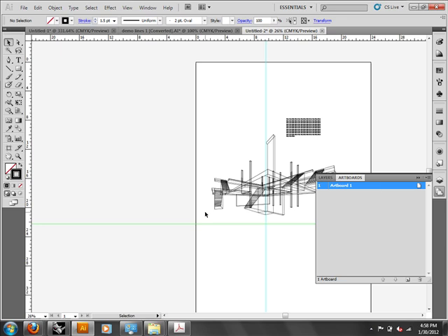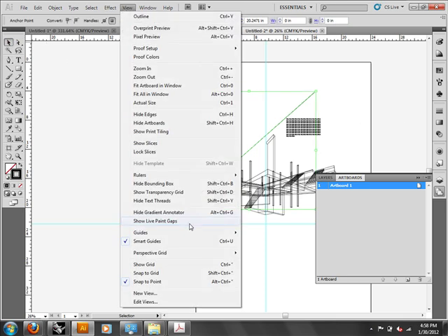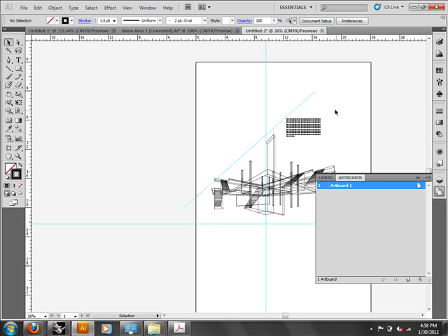So if you wanted to have a registration line, or make the line for your vanishing point or horizon a guideline, you could do that. You don't need to, but you can make a line a guideline. Just make a line, go into Guides, Make Guide, and that will turn the line you just made into a guideline. I prefer to actually draw my lines as if they were drawn, and then use those for guides. I just have them locked and snap to them. But you guys may use guides, so that's how guides work.